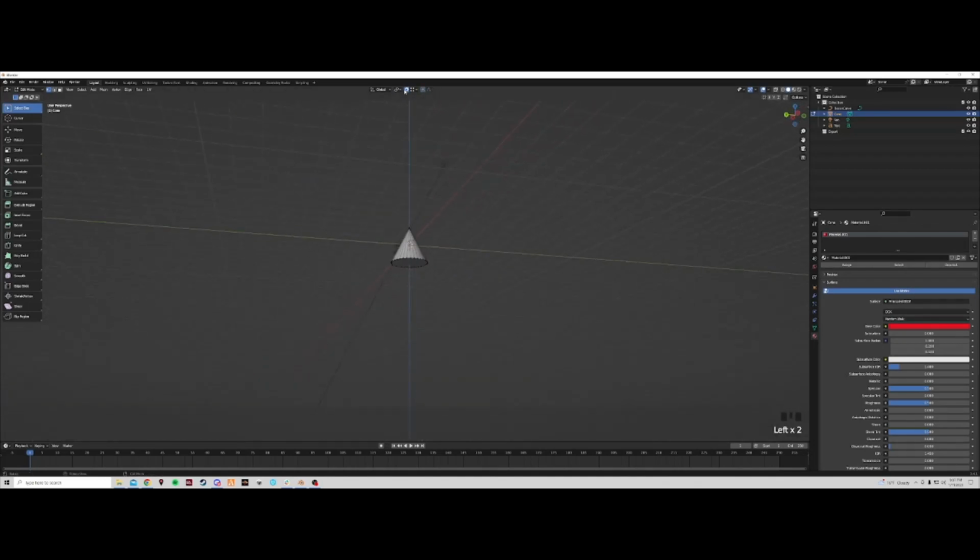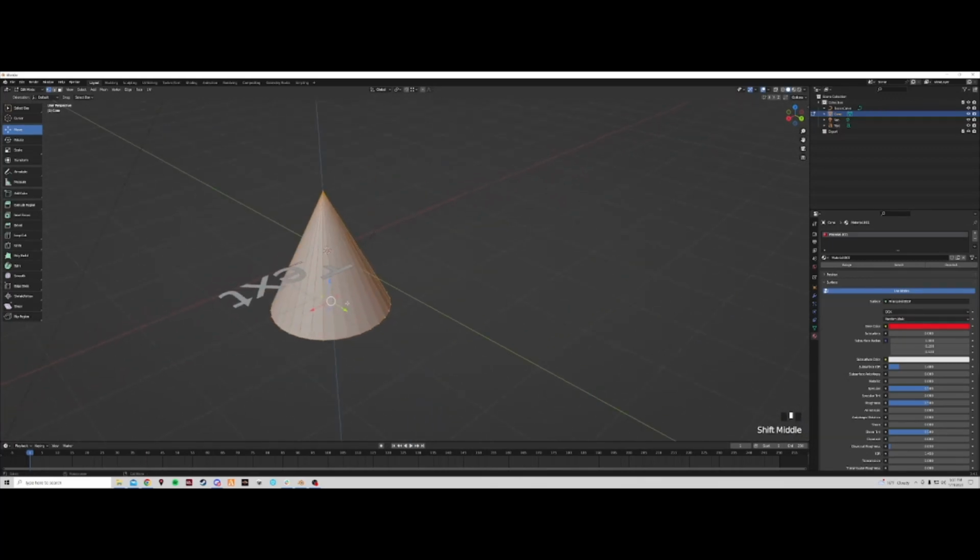Okay, I'm going to turn that off, turn snapping off. Over here, this is just turning on the visibility for certain things in your scene. Go through that list, figure out what you want to see and don't see. Turn off all meshes, curves, surfaces, turn off text, things like that. It makes it disappear in your view. This one right here is gizmo. It's like your move tool that I can't see right now. Why can't I? Oh, I didn't have anything selected. If I turn this off, you can't see the tool.